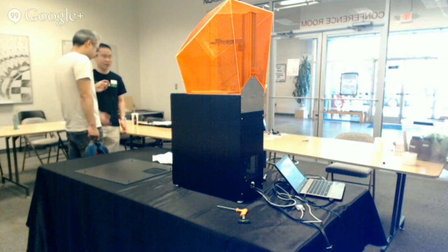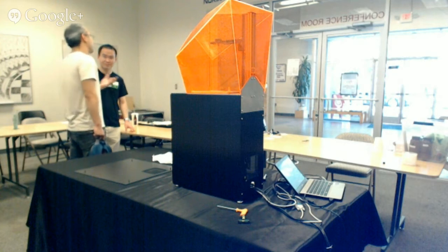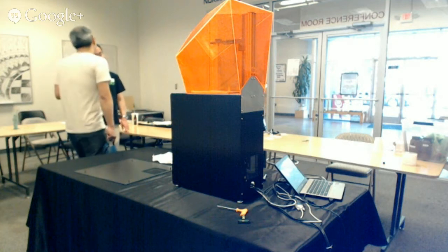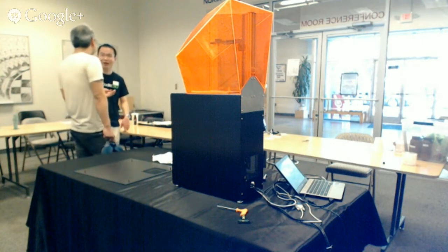You're telling me that the resin you're using is strong enough to do injection molding with this as the mold? In theory, yes, if it's properly designed. This has a terrible design flaw. You will notice that at the injection nozzle, where the 10 tons of force comes down here, that is the thinnest part. So this does not withstand injection molding. But I will thicken it, and then it should work.